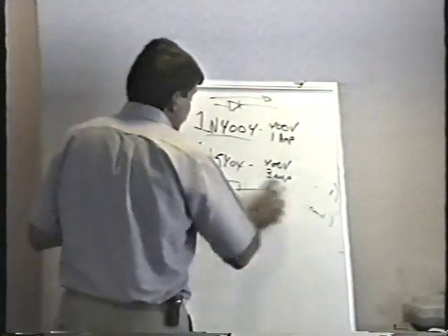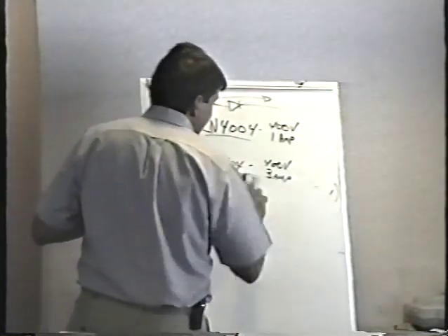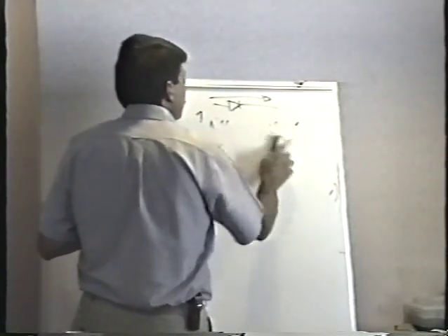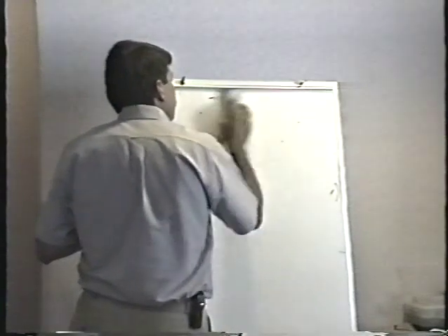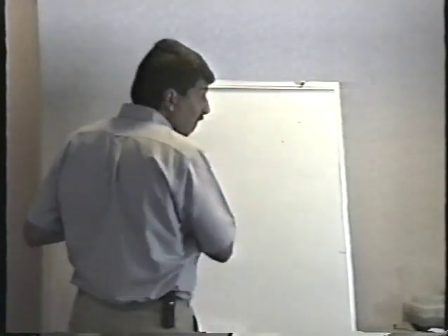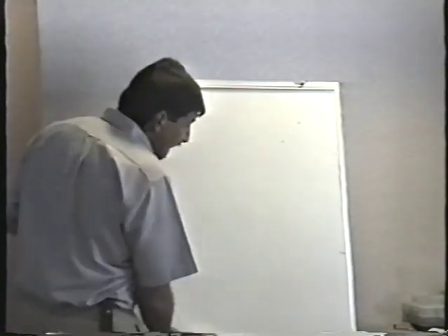Diodes, there's no question at all about checking diodes. Like I said, most of the time you can test them in circuit. Generally, my philosophy regarding checking parts in circuit, that is, as they're mounted on the boards themselves, is that I always try checking everything in circuit first.